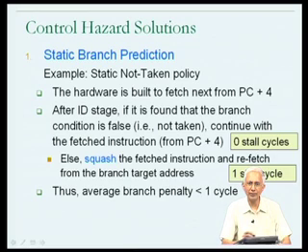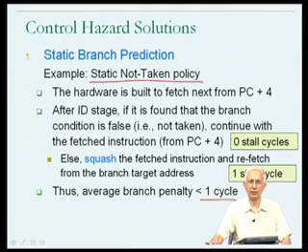It will lead to a little bit more complication in the pipeline, in that there must be built into the pipeline the capability of detecting that the condition was wrongly predicted, and that therefore an annulled instruction must be passed through the pipeline without updating the processor state. So, some complication in the design of the processor pipeline. But this is an idea which seems to make some sense in the light of improving the performance on average, reducing the number of stall cycles on average for a program. And there could be other static policies, but this is one example which seems to make good sense.